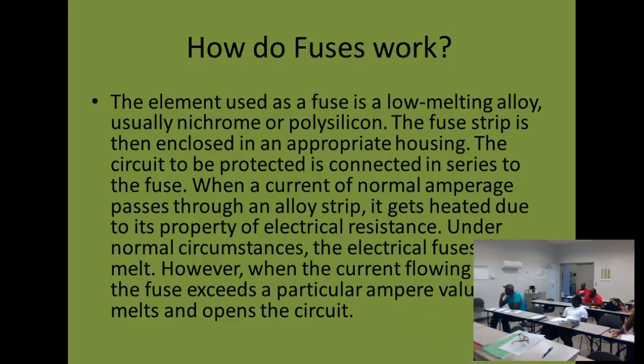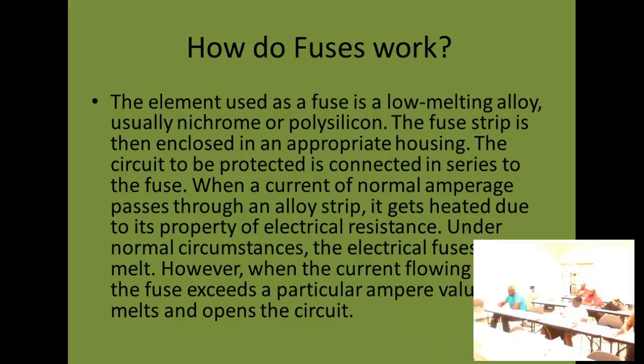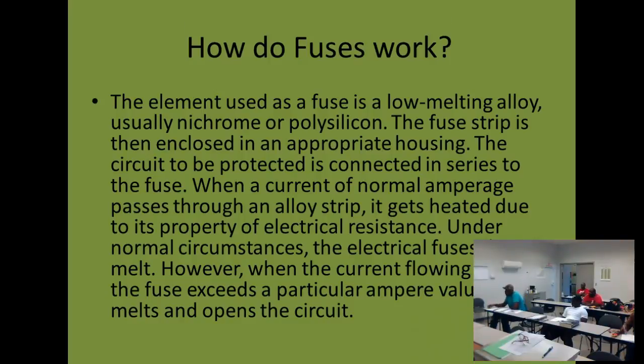If I take my meter right now, I'm running down the path. It's going to say 0. There's a good chance when I cut it off, it may say 120. That depends on what? What kind of resistance is on down the line. Okay?